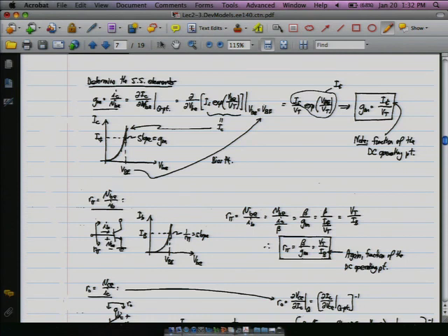Well, that's true if you're talking about voltage gain, but really the basic mechanism of a transistor is you take an input voltage and you turn that into an output current, so you end up with a transconductance, and that is, I think, a little bit more fundamental of a gain parameter.